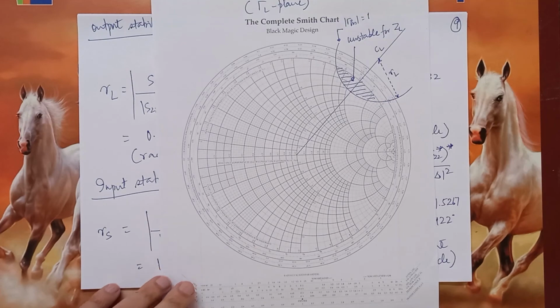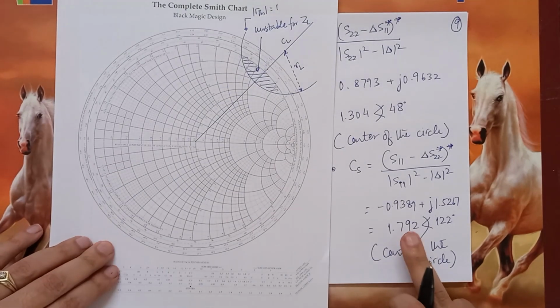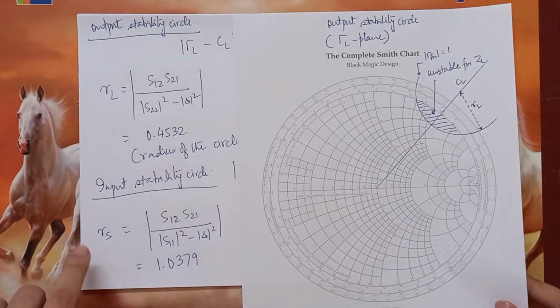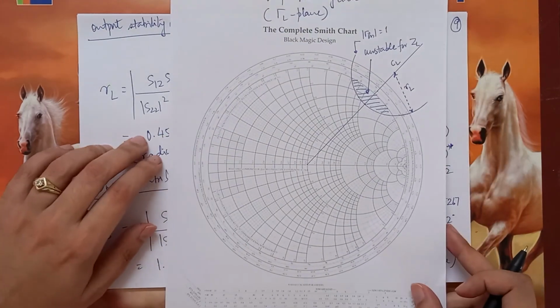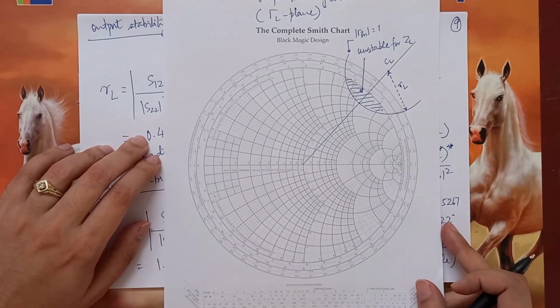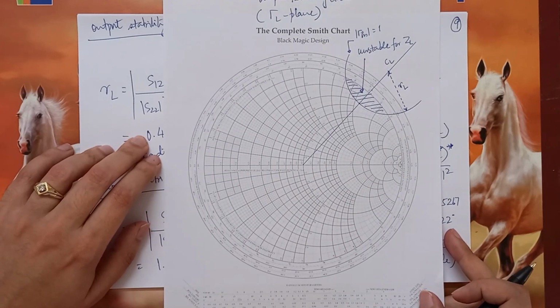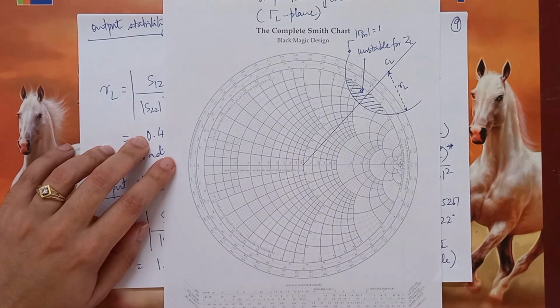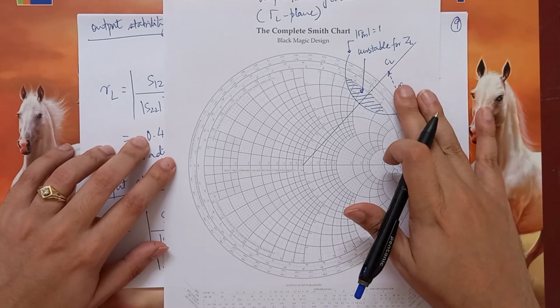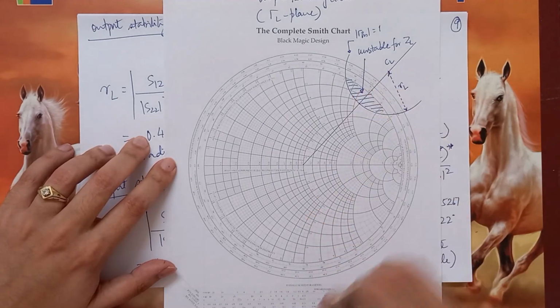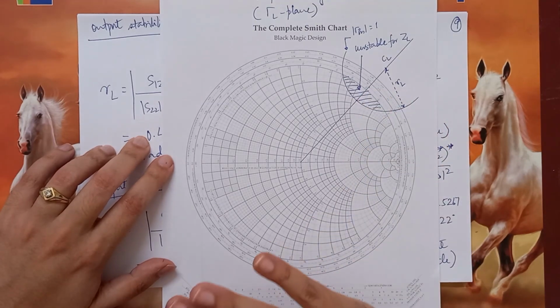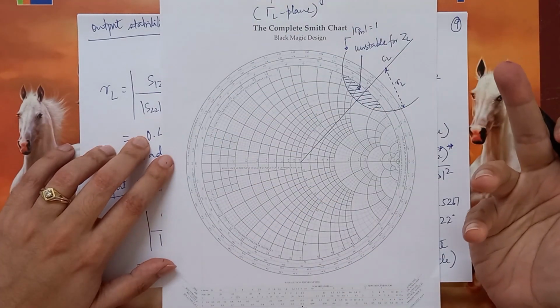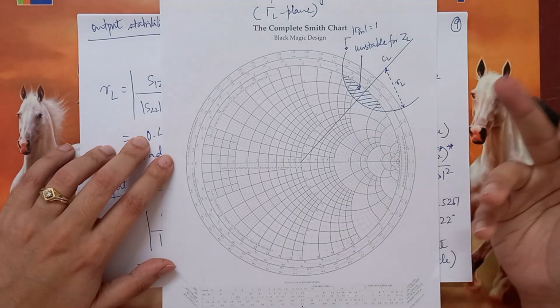Likewise, what you can do, you can take a Smith chart, you can plot what is CS, what is RS, and accordingly draw the circle. That will be a good exercise for you to see where the circle will lie and how much of the Smith chart it engulfs, if at all. So one thing we have proved over here is that definitely the circuit could be potentially unstable from the output side. Now the input side also could be potentially unstable, and that is for you to find out.